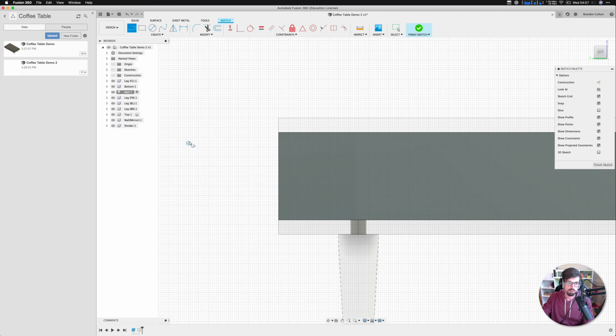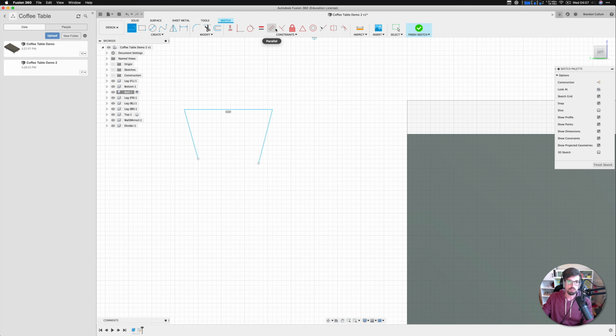This is just kind of an easier way, at least for me. You can draw out the shape that you're looking for, and then start constraining it outside. So the first thing I wanna do is these need to be equal in length. And as always, if you start just playing around with it, you can kind of see what else you still need to do. We're going to do symmetry on this. So we're going to do a construction line where we have the symmetry.